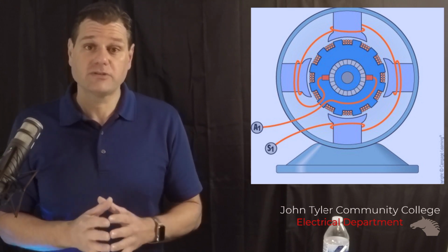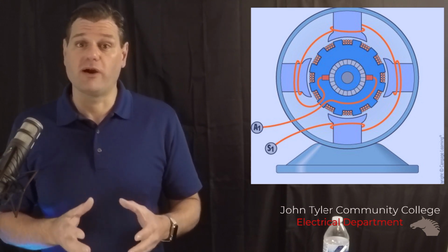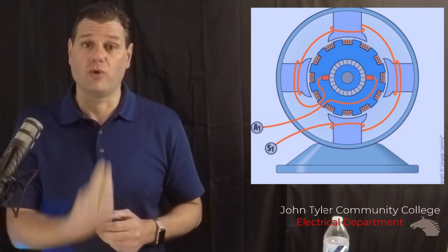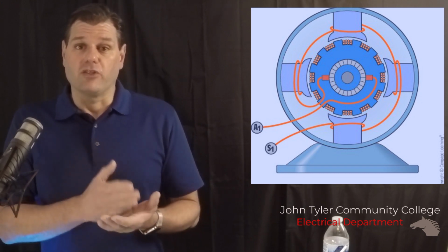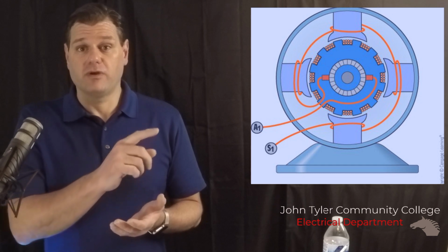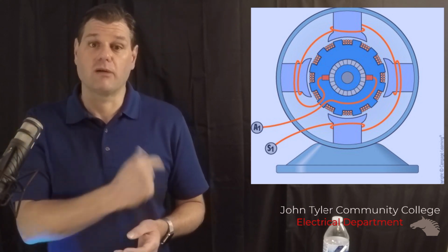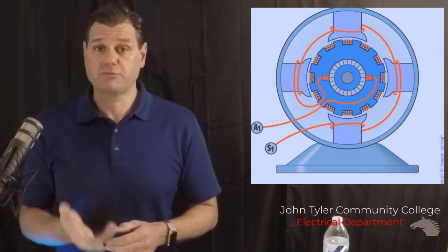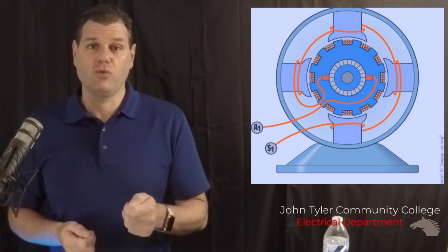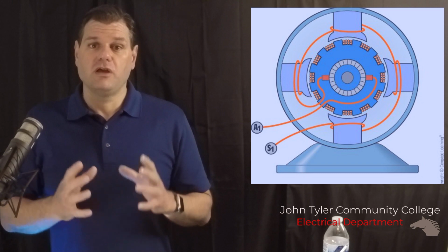It's very rare, it happens. I've seen a couple motors that were internally wired just like that, but typically you'll see all wires come out. Now the pole piece has the series winding, and it's going to go all the way around. So it's a wrap on each pole piece, and then it's going to come out as S1. So in this particular motor, we'd hook up S1 and A1, rotate the armature, and that would allow us to